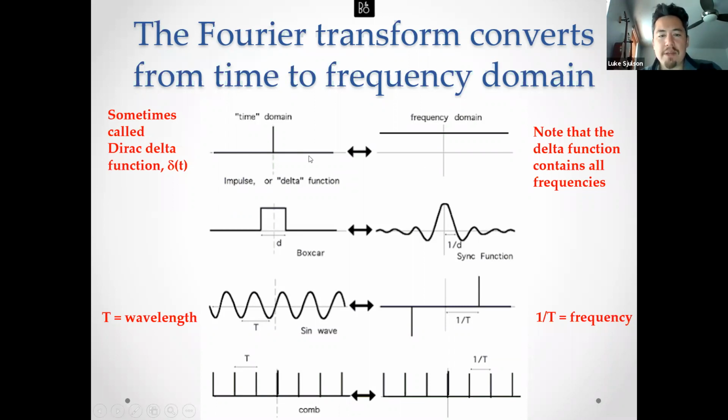So here we have time on this axis, and then we have intensity, however you want to phrase it, on this axis. Here you have frequency on this axis, and then how much of the frequency is up here, right? So this is a frequency of 0. One thing that's maybe a little counterintuitive about this is that you have positive and negative frequencies here. You could just look at half of it, but the reason you have positive and negative frequencies is that these values here are actually complex values.